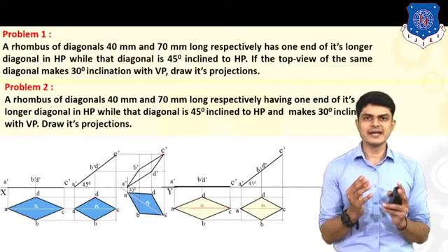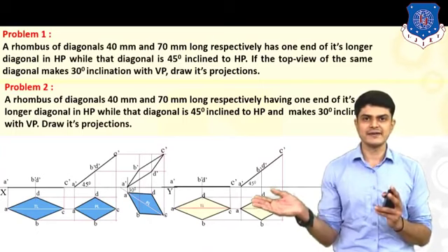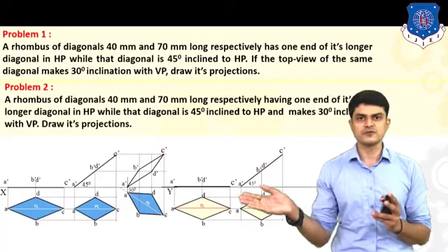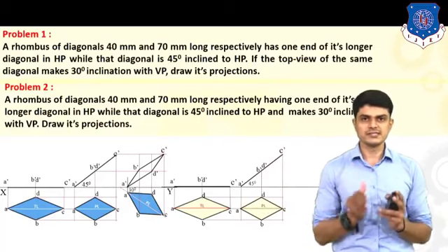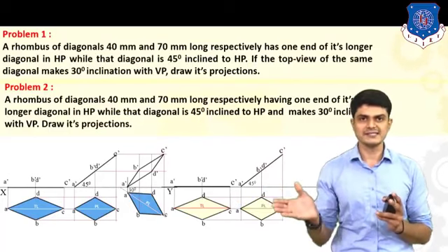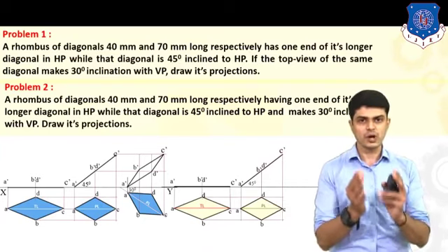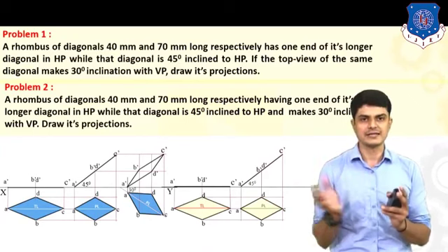So, what is a real diagonal? Real diagonal is denoted by red in the first stage, as you can see, which we have taken to draw our first stage true shape. So this is nothing but your true length. But in the second case, we are having a shorter length of the diagonal, which is also known as the top view of the diagonal or your plan length.